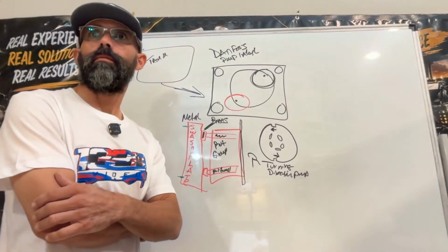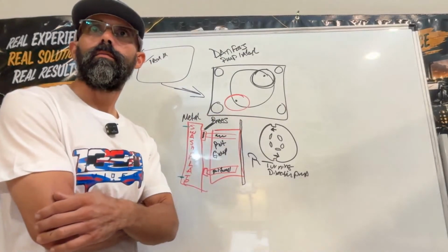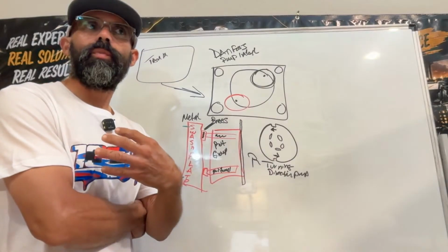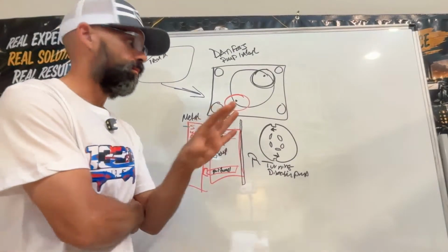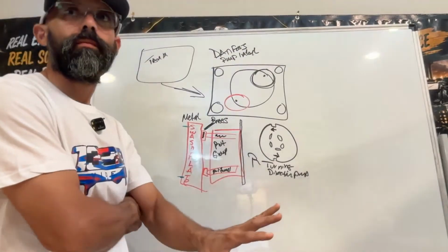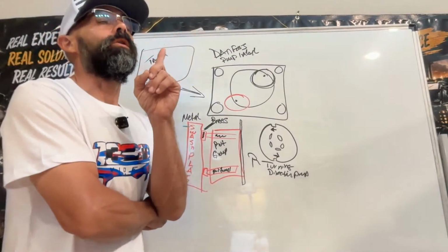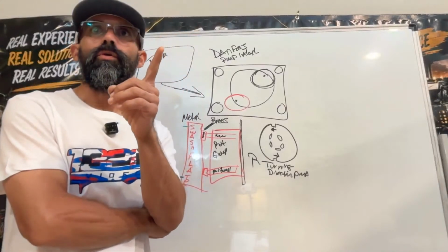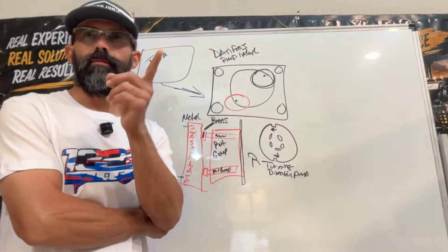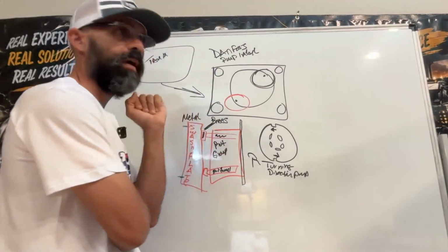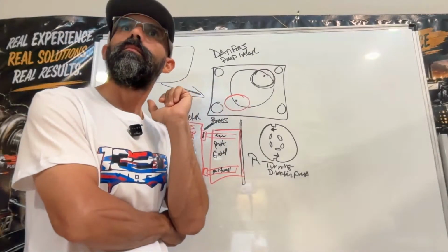Well, something happened. Most of the parts are new, because I rebuilt it, but some of the parts on a pump you don't need to buy new, depending on the condition. You can save them. For example, if the slippers are okay, you can reuse them. Just lap them.